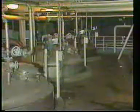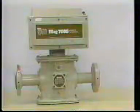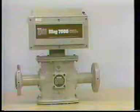As we said earlier, another problem that can be expected from this type of meter is coating of the electrodes by non-conductive material, either the electrolytic byproducts or clinging process material. This buildup is usually gradual, but its effects can be significant over time. Some magnetic flow meters are available with removable electrodes, which may be inspected periodically and cleaned if necessary without dismantling the meter. Ultrasonic cleaning systems are also available to remove accumulated non-conductive material without opening the system.